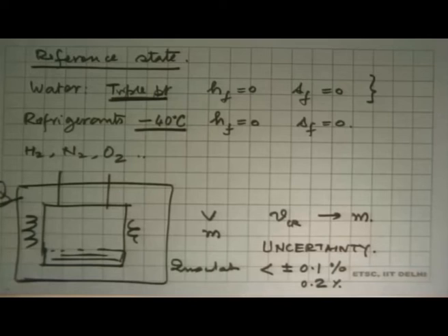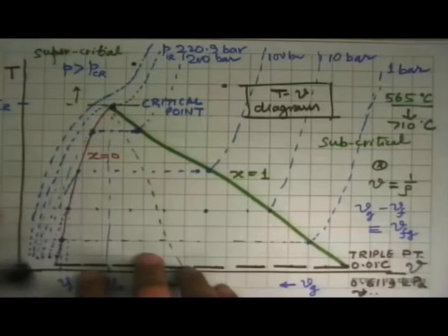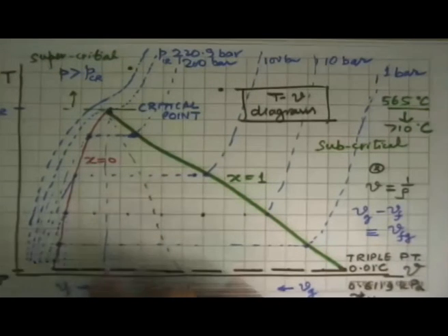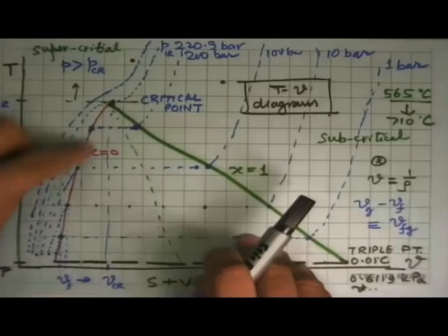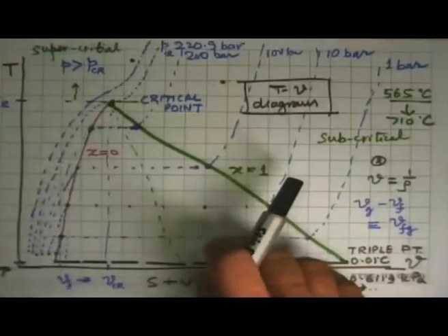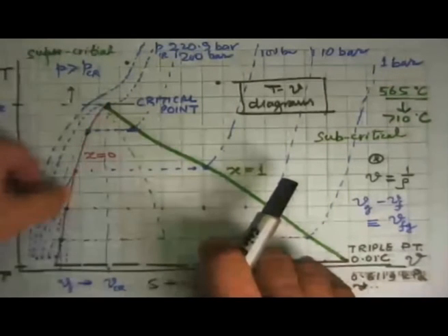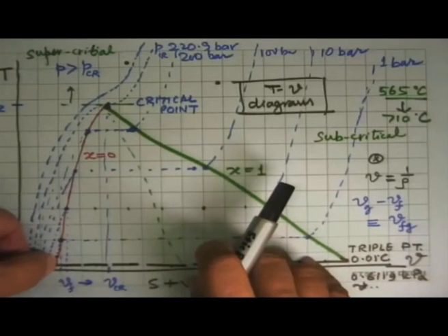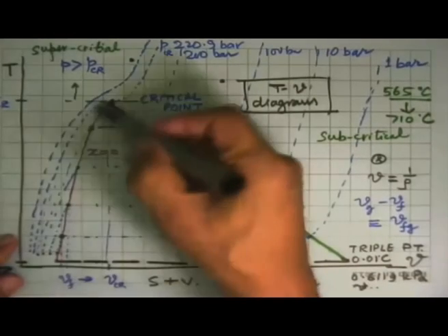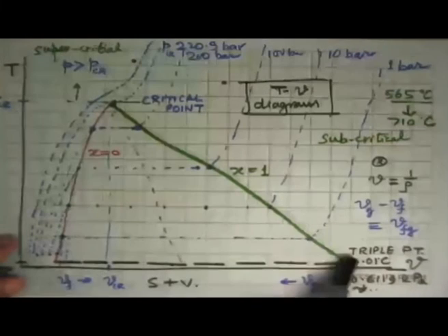Okay, what is the saturated liquid line? On this diagram, I've shown a T-v diagram, and tomorrow I will add on to it, and we will make T-s diagrams, p-h diagrams, any combination of those diagrams. Everywhere we will get a locus of points which correspond to x equal to 0, which is the saturated liquid. That line which joins all the points of x equal to 0 is called the saturated liquid line. So this line is the saturated liquid line, this is the saturated vapor line.